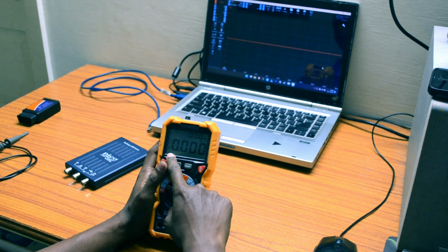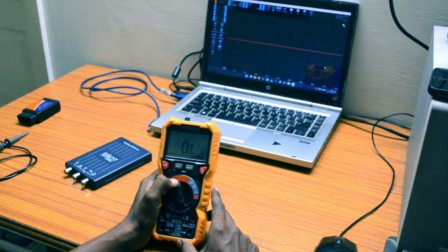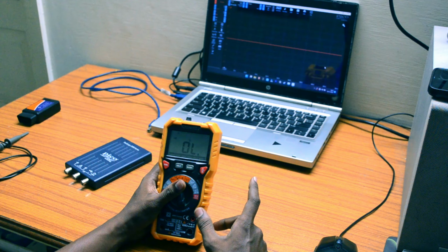In this resistance measurements, we can start from 0 or 1 ohm up to few mega ohms. In few multimeters, there will be a set of range for resistance such as 0 to 200 ohms is one setting, from 200 to 5k is one setting, from 5k to 1 mega is one more setting. Or you can have a auto ranging multimeter which has full resistance scale in single setting. In the same setting, we can measure the continuity of the wire, that is, it usually beeps which indicates a wire continuity is proper, and there is a mode to check the diodes as well.